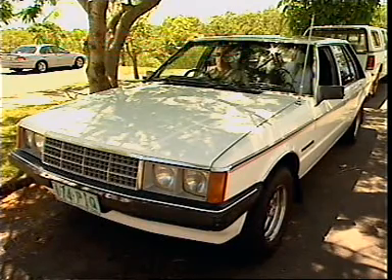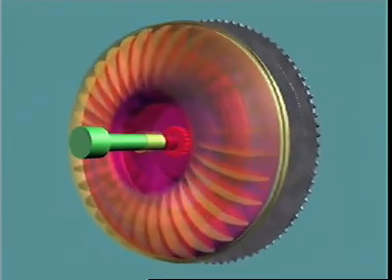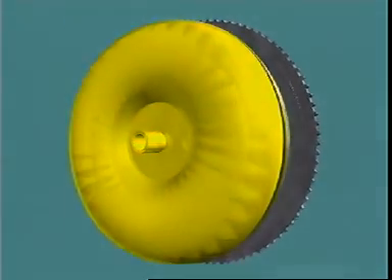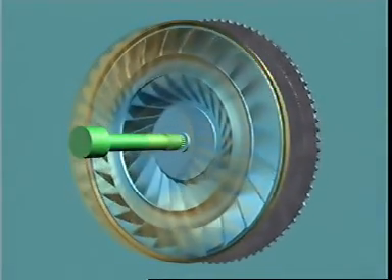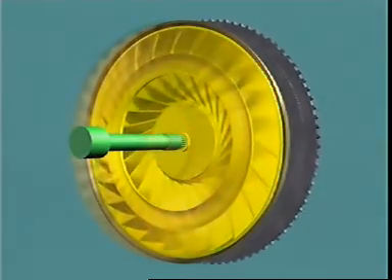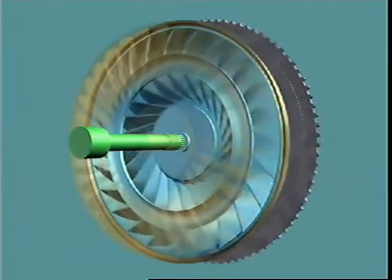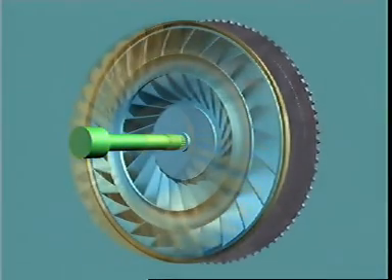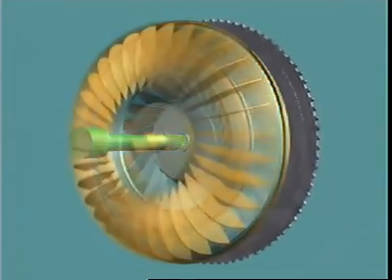When the engine starts and idles, the transmission pump rapidly fills and pressurizes the converter. The impeller is driven by the engine and turns at crankshaft speed. With the selector lever in the neutral or park position, the turbine also rotates, carried around by momentum of the fluid. When a drive position is selected, the turbine shaft is locked to the transmission output shaft through the transmission gearing, and the turbine comes to a halt.